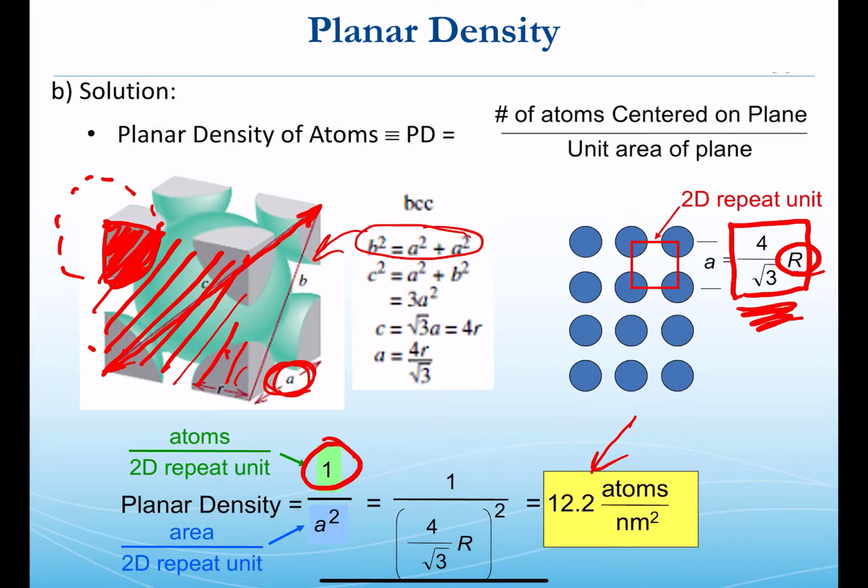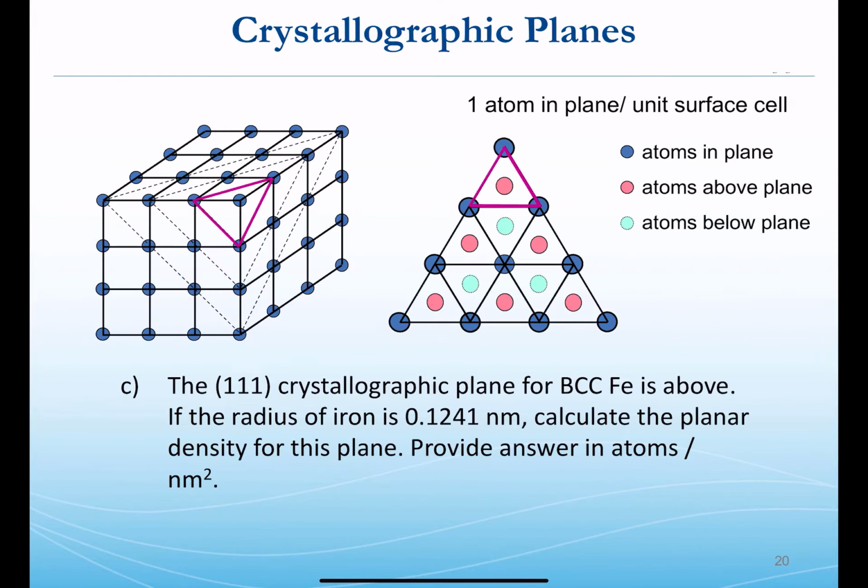Okay, again, hopefully that means something to you. That's now telling us how many atoms lie in this plane across the material. So 12.2. Values that are very high might represent a higher density of atoms to push through or to corrode through. Values that are low might be more porous, and very small molecules like hydrogen gas might seep through that direction preferentially, as is the case with hydrogen storage for fuel cells and other kinds of gas storage problems in engineering for aerospace, as an example.